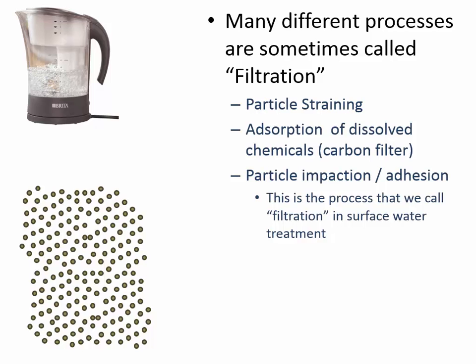On the left, all those little dots, that's meant to mean sand. So here is sand. What is the empty space between the sand particles? Do you remember the technical term for that? Voids. Right. So this is exaggerating the size of the voids. In reality, the voids are approximately the same size as the sand grains themselves, maybe a little bit smaller.